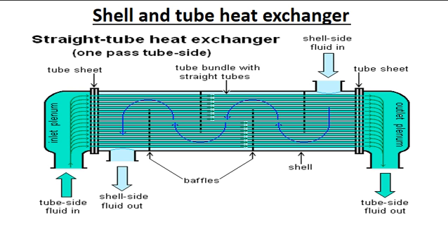A set of tubes is called the tube bundle and can be made up of several types of tubes: plain, longitudinally finned, etc. Shell and tube heat exchangers are typically used for high pressure applications with pressures greater than 30 bar and temperatures greater than 260 degrees Celsius. This is because the shell and tube heat exchangers are robust due to their shape.